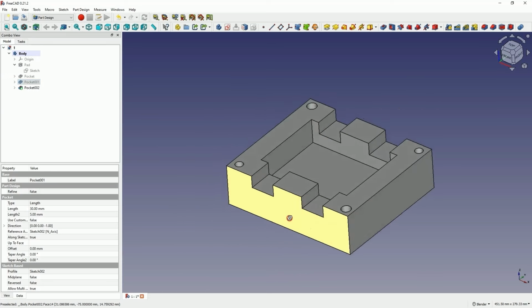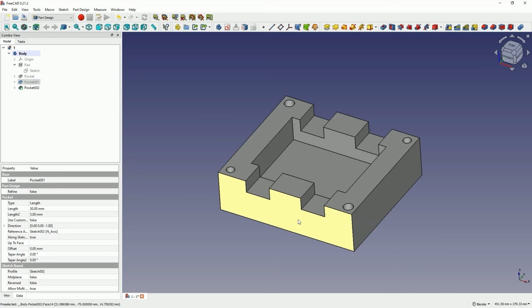Another basic but frequently used operations in 3D modeling are the operations of adding chamfers and fillets. These are the two operations. They work in such a way that we can add a chamfer or a fillet for one specified edge or for several specified edges, or we can select an entire face, and then all edges belonging to that face will be chamfered or filleted. Let's add some fillets and some chamfers here.